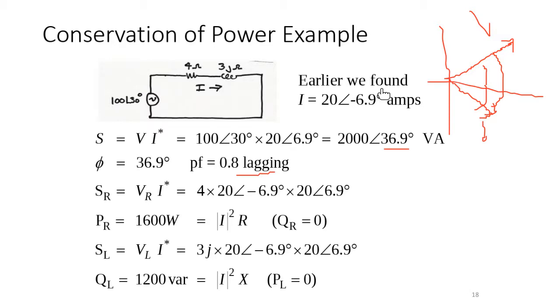So if I stop in here, the voltage comes first. Always stop on the other side. For example, you stop in this line here. The voltage touches this line before the current. We go anti-clockwise. Therefore, voltage touches first, and the current crosses second. Therefore, current is lagging the voltage. Or you look at it in here, then you can find this. The current is lagging.